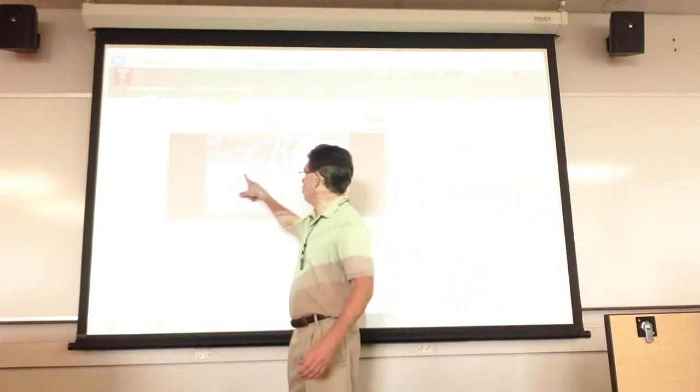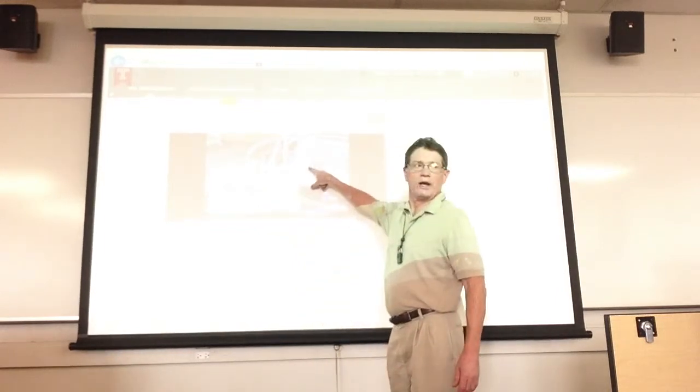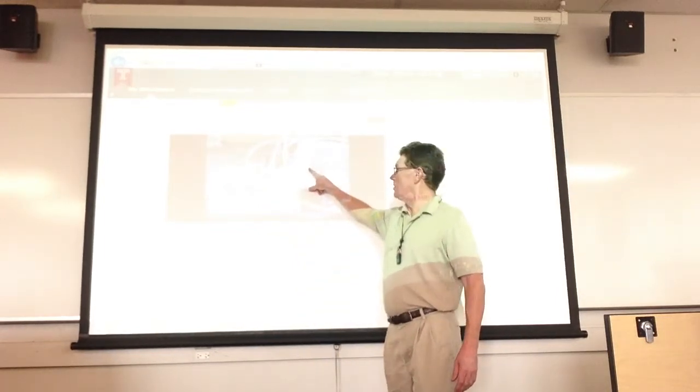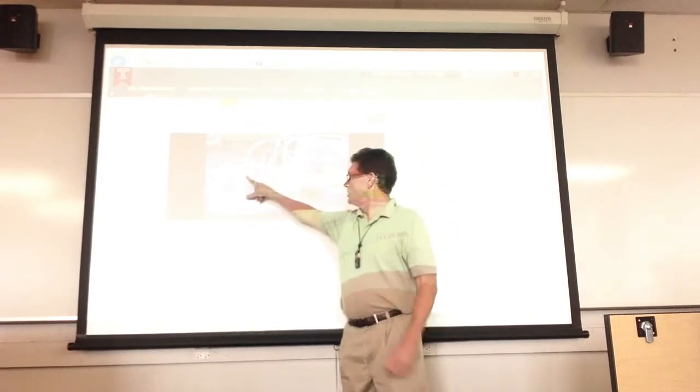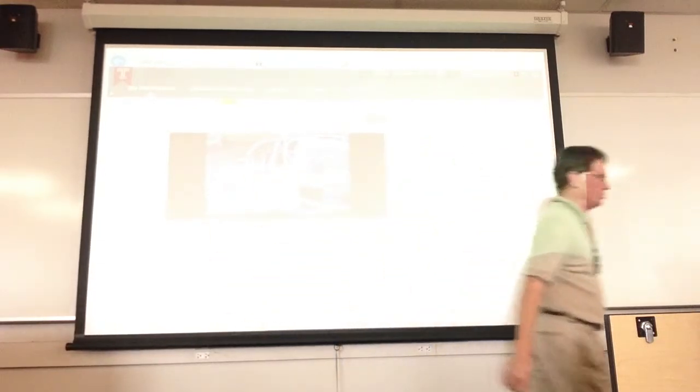So it comes back. This LED down here is sitting on port B, pin 0, which is the first one there. So it's port B, pin 0, turn that one on, then shut it off, and then go up here. And then I'll show you how to do the I/O stuff with those switches in a second. And there's a delay of a second in between them, just so you can see it.